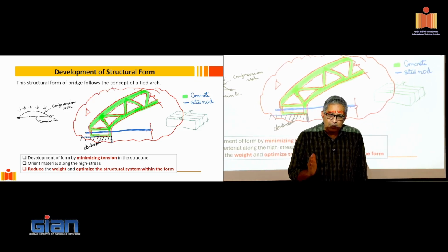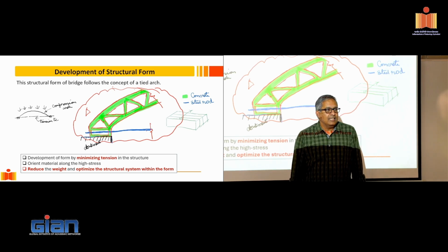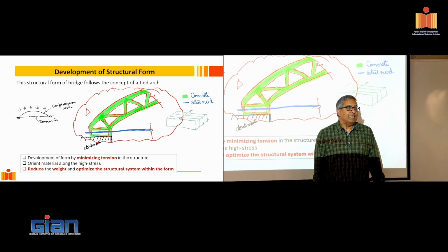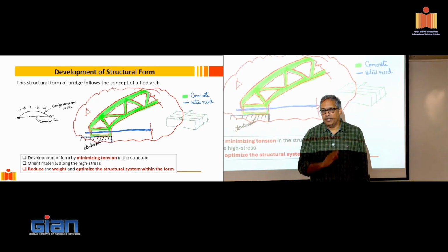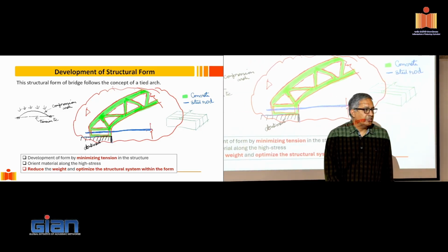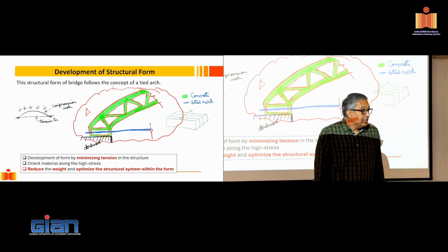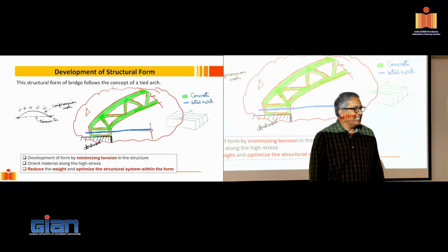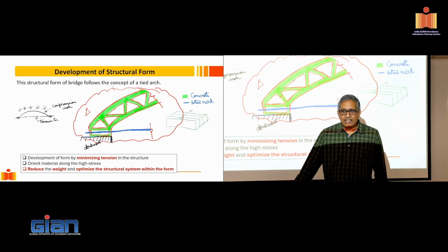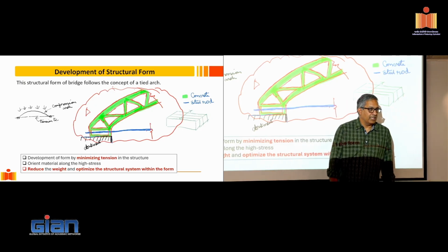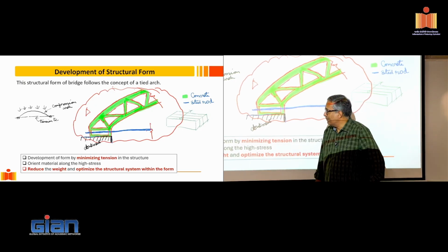Right? Some of the best bridges that were designed at the turn of the 19th century by the British were made of masonry, and they're all arch bridges. And they're still standing today. Right? And the reason is we are using material where it is the strongest. They're masonry structures. They're taking the traffic of 25-ton wheel loads that we are operating with the railways today.